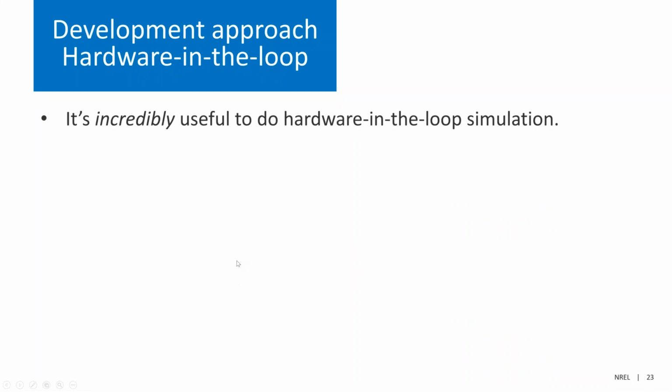It turns out when you're designing wind turbines, especially wind turbine controllers, it's incredibly useful to create a system that allows you to do hardware-in-the-loop simulation. And what do I mean by that? What I mean is you have your controller running where it thinks it's controlling the real wind turbine, but you're giving it simulated inputs. You're controlling the wind in a simulation. You don't have to have a wind tunnel. In fact, you don't even have to have a dynamometer or a drive system. You're just feeding it simulated inputs to make sure that it's responding to those simulated inputs properly.